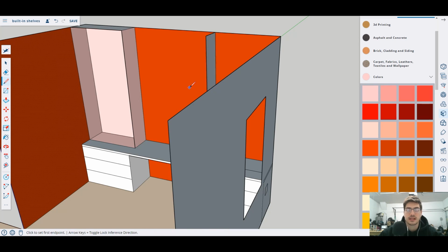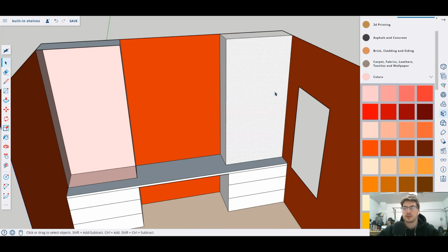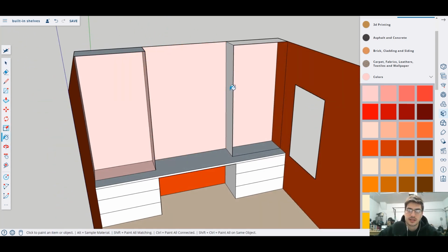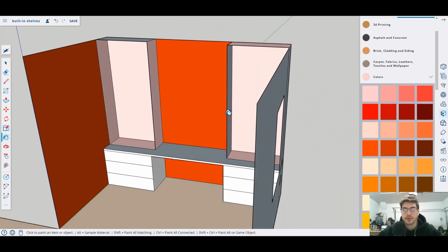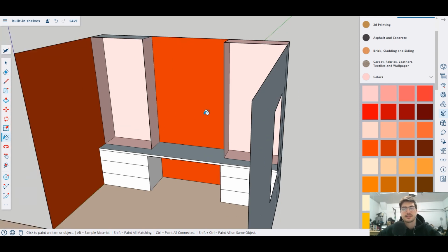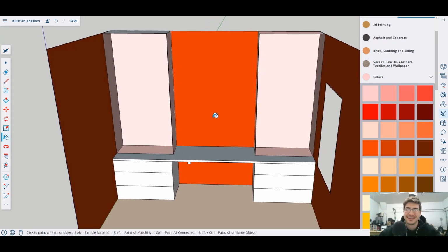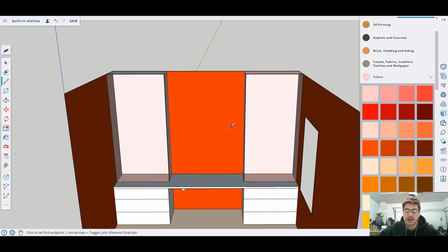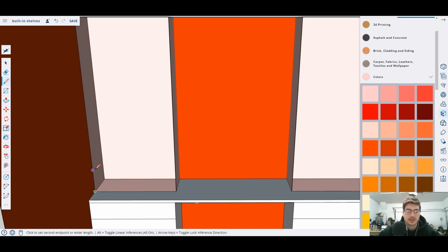And this is not like a beginner, my first SketchUp tutorial, but it's pretty sweet how often you can do almost everything in a model, especially for home renovations and stuff, with this SketchUp auto snap tool, where it'll pick a blue, green, or red axis, one of your three axes, and snap to it, so that you can skip the tedious process of aligning everything. You can just snap to an axis. Okay, so a bit of a tangent there, but we're good.